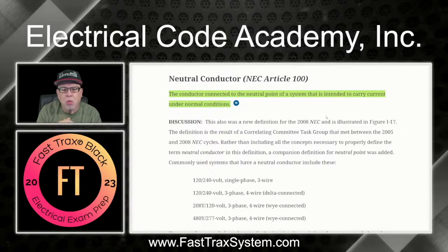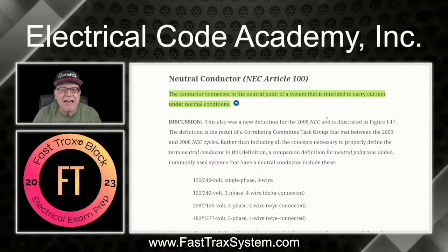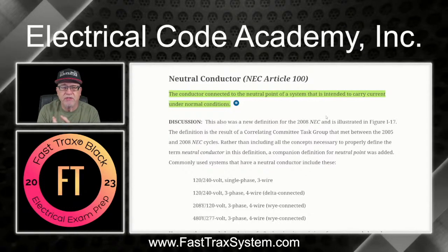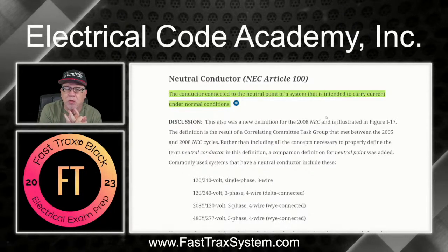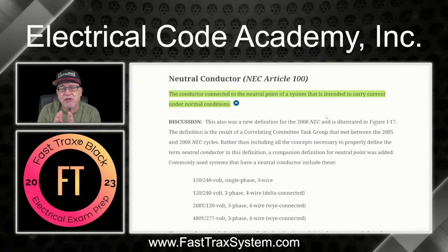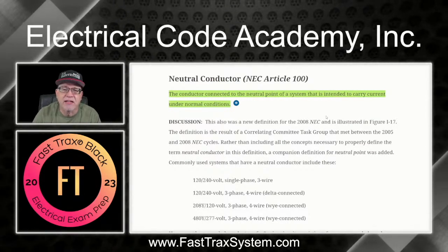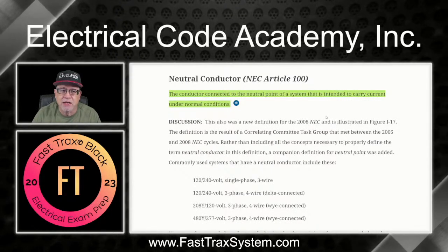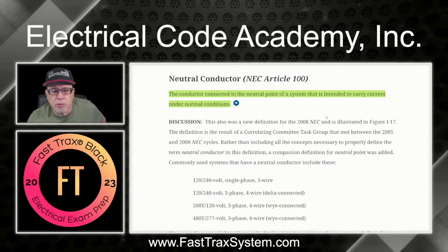And then, of course, we'll go on into the second part, where we'll look at how it's applied to the service and the calculations that you have to do, and what's the minimum size that's required by 250.102(C)(1), and how that's applied. And we'll look at things like 250.24(D), and we'll see how you're sizing those grounded conductors and things like that. So it's a lot. Make sure you buckle up for it, because we're going to cover a lot in this series. All right, so let's look at this discussion.